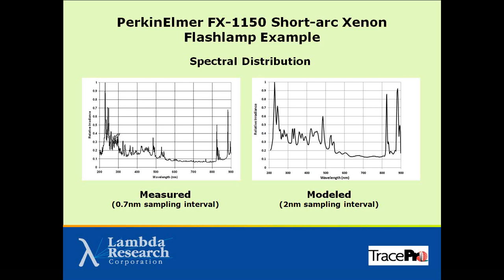Also measured the spectrum of the lamp and use that to create a surface source property, the spectrum in TracePro. You see here, this is measured with a spectrometer at 0.7 nanometer sampling interval. Ran the ray trace in TracePro with a 2 nanometer sampling interval, and you can see again good agreement between the two versions.